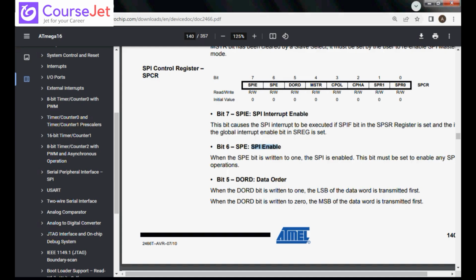SPI communication is provided, which has multiple options. One is that the pin works like input output, and the alternate function is SPI, right? We are not dedicating particular pins of our microcontroller to SPI communication. We are using pins which have alternate functions.